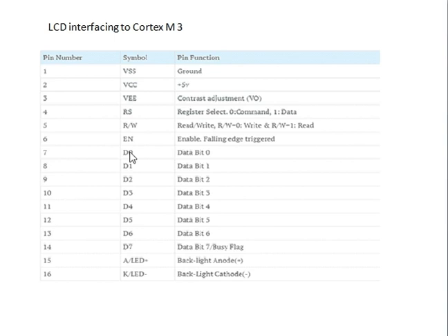In Arduino, probably we might have used the LCD header file. There 4 pins were used for transmitting data, which were addressed as D0, D1, D2 and D3. Over here we are using 8 bit mode, and that mode has to be addressed in the program. And along with that, control signals which we need to send to the LCD module to make it understand whether we are transferring commands or data.